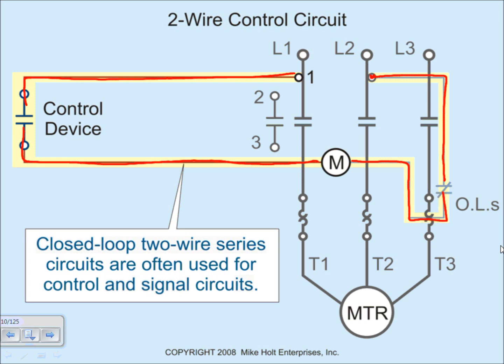So one advantage of a series circuit is control. In control, it makes a lot of sense to put things in series. For example, I want you guys to look at the overload and the magnet starter and this contactor device. They're all in series, tied to a voltage of 480 right here. That's a good application of a series circuit, where control is really good.